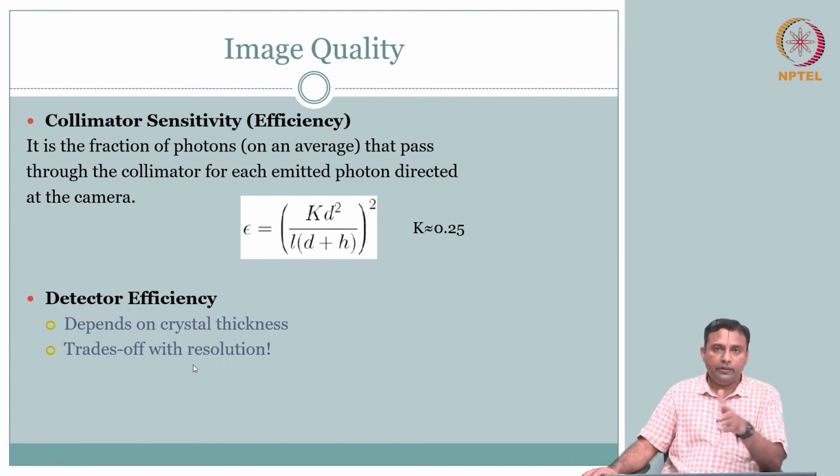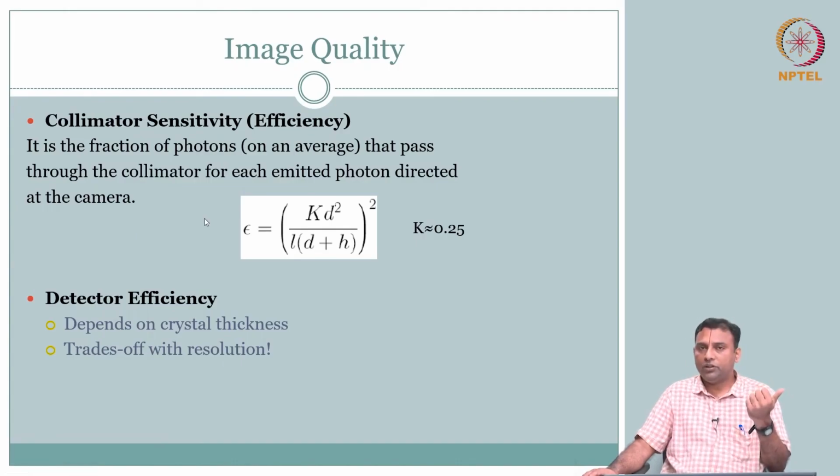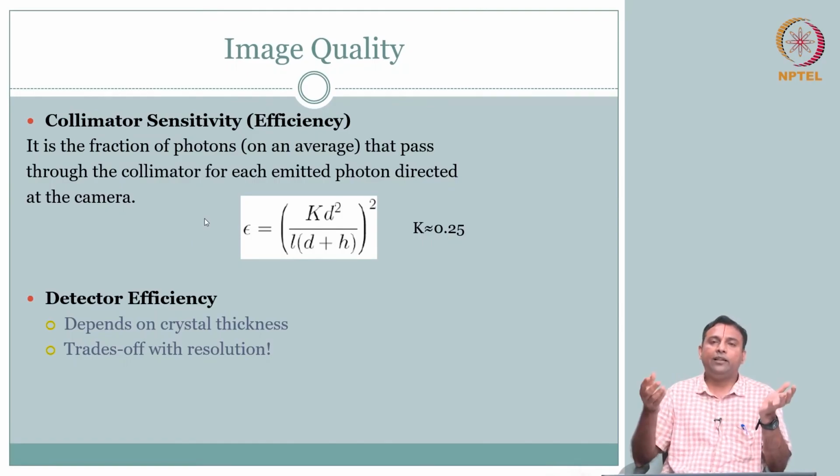Okay. And then once you get the x comma y z, we talked about what image is shown, right. Okay. So much for image quality with respect to resolution and detector efficiency. Of course, we need to talk about noise. If we talk about noise, we talk about signal to noise ratio. When we talk about signal to noise ratio, we need to talk about more importantly the contrast. But here, as you would notice, nothing much has changed, right. You get n photons, only thing is it is in the gamma energy range. So, the photons arriving at the detector, you have the same Poisson statistics.